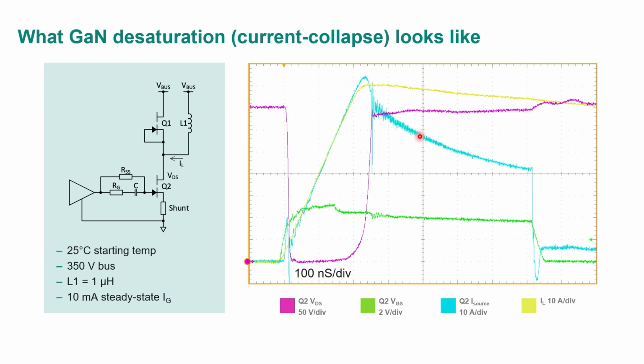As time goes on, it supports less and less current. So this current is limited by the transistor itself. This is known as current collapse. Here I have massive dissipation because I have simultaneously almost 350 volts and 50 amps or something like that. Each division here is about 5 kW: 5, 10, 15, 20, 25 kW of peak power dissipation in the device.